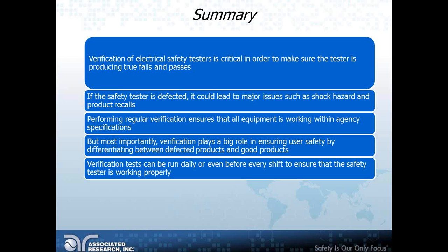to get into. Additionally, electrical safety testing instruments contain built-in suppressors that are designed to protect the unit circuitry. But at the same time, these are electrical devices after all, so damage to such suppressors can cause false readings on an instrument. But taking simple steps to run daily verifications, like the ones that we went over, can spare a great deal of trouble and effort down the road, and can help avoid costly redesigns or product recalls.